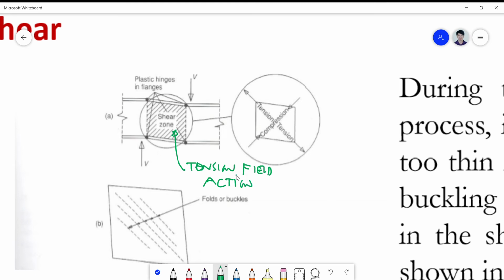Shear stresses, class, are simply tension stresses, even in concrete. In fact, when we design shear, we call it diagonal tension in concrete. Right? We are expecting cracks to happen diagonally. In fact, the stirrups are much more efficient in concrete when you place them diagonally. It's just that nobody uses them because it's easier to place them straight.